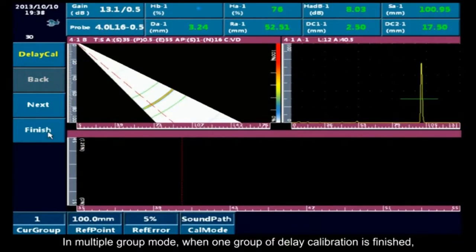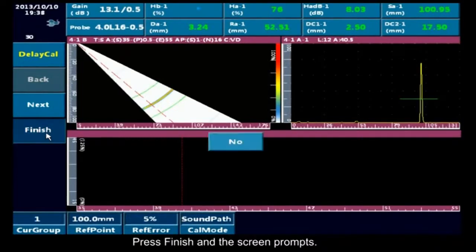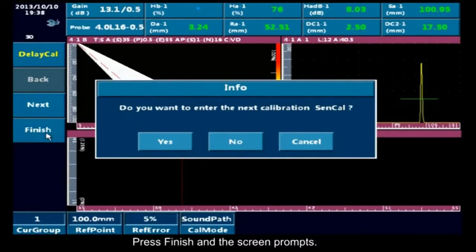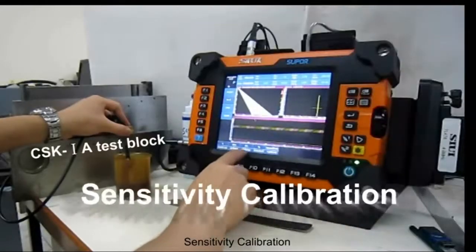In multiple group mode, when one group of delay calibration is finished, click Next to go to the delay calibration of the next group of scan images. Press Finish, and the screen prompts, do you want to enter the next calibration, sensitivity calibration? Click Yes to enter the sensitivity calibration.